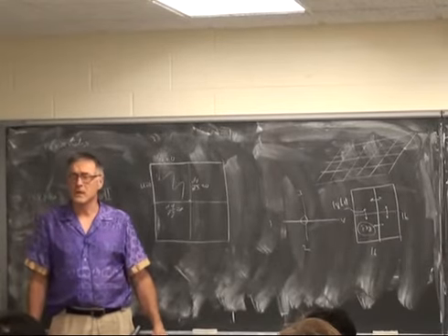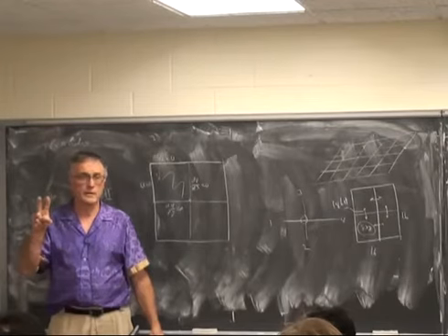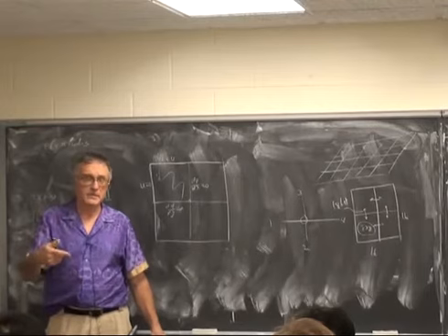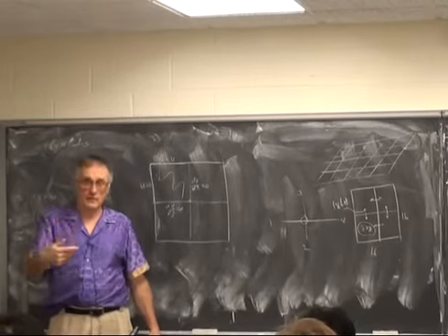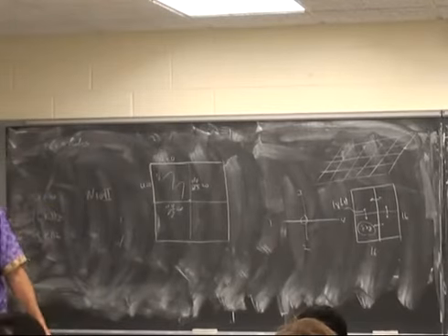It's not a single cycle multiplier, it's a 2-cycle multiplier and a 2-cycle adder. So you'd have to change the state machine in the CPU to put it in an idle state in a multiply and add instruction. But it wouldn't be a huge job.